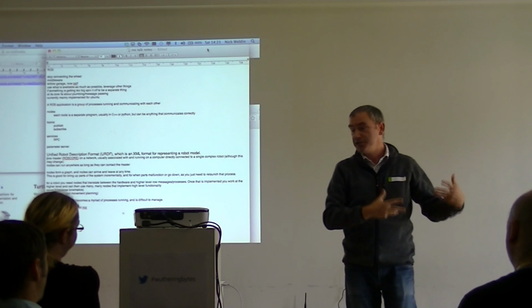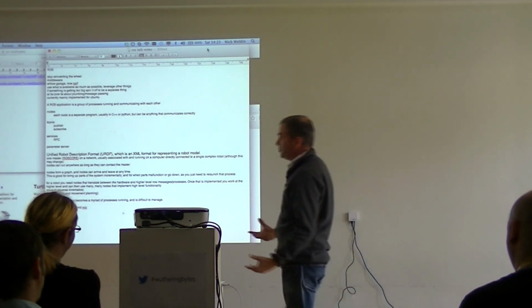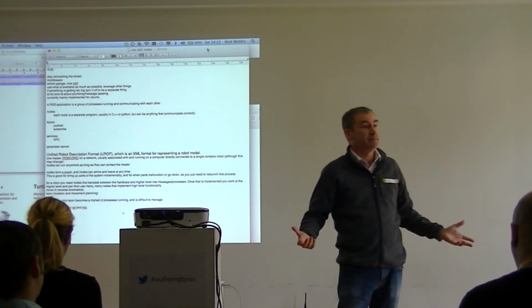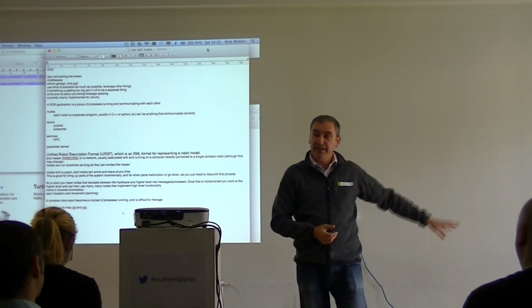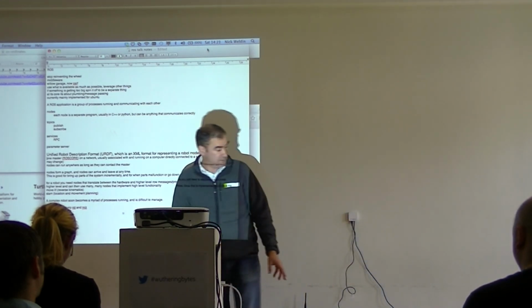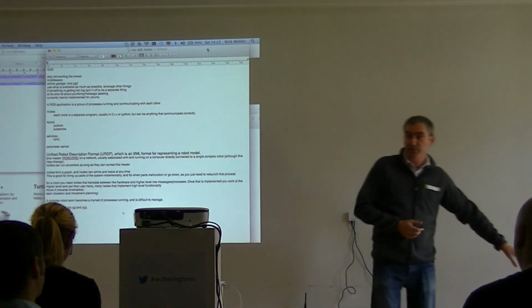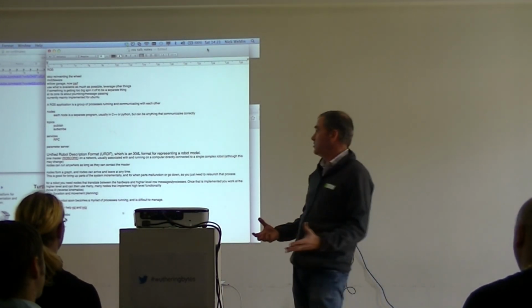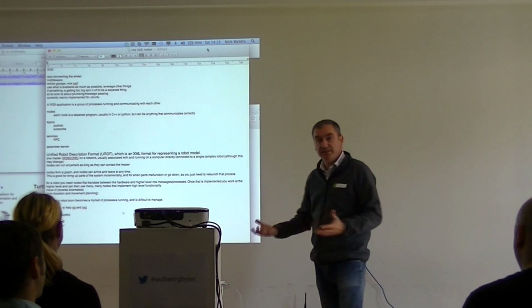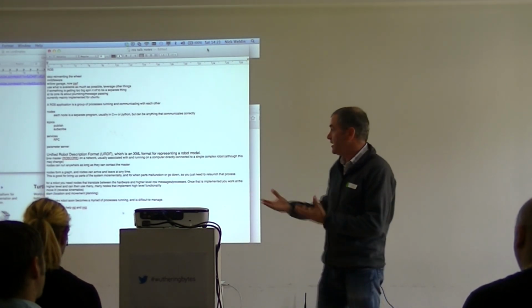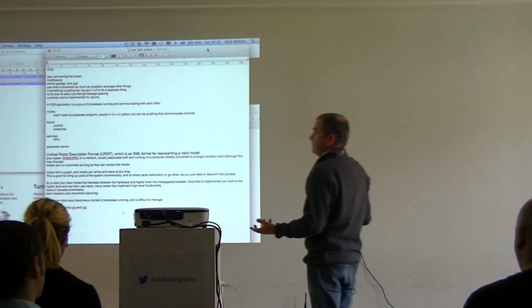And once you've got that URDF model, you can then interface it to pretty much all the stuff that ROS does. So your really fiddly bit is getting your URDF model done. We cheated and bought one of their cheaper robots, so you get your URDF model already. But because it's all open source, there's lots of them out there. And the documentation about how to do it is out there.